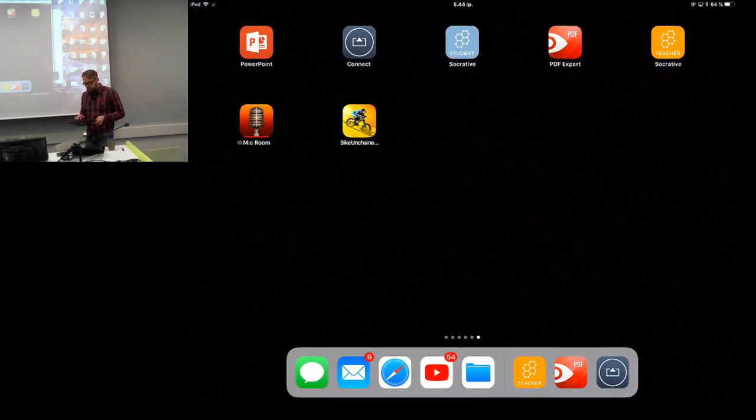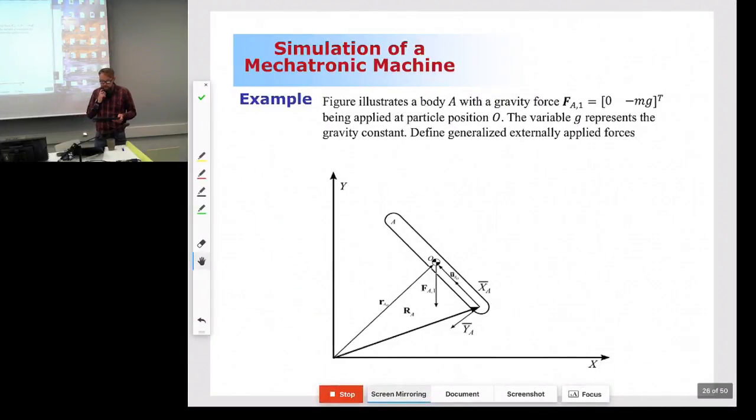All right. So let's practice a little more. So now I have here a real problem. The real problem is a beam-like body, and here in my beam-like body there is a force that is applied at the center of mass. The center of mass is the middle of the beam-like body, and the body coordinate system is located at one end of the beam-like body. Now my first question is, when we express this using generalized coordinates, there are going to be three components. The third, final component will be associated with angle theta. Is that going to be 0 or non-zero?